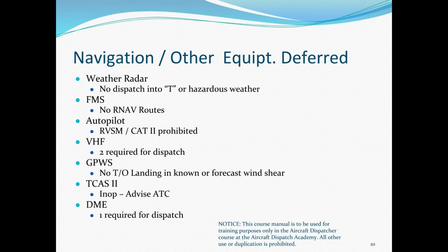And it's really not too huge of a deal, but it always sucks when you have a FMS deferral because you cannot use any satellite-based navigation at all. You have to plan the flight using what we call green needles. So all ground-based navigational aids. And when we say green needles, it's referring to the actual instrument inside the airplane.